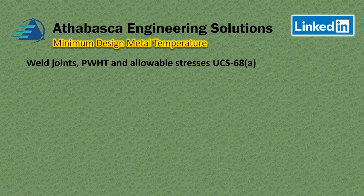To weld joints, post-weld heat treating, and allowable stresses as described in the new section called UCS-68A. And UCS-68 provides supplemental design rules for carbon and low alloy steels with regards to weld joint categories as described in Section 8 Division 1, the joint types, and the post-weld heat treatment requirements and allowable stress values.